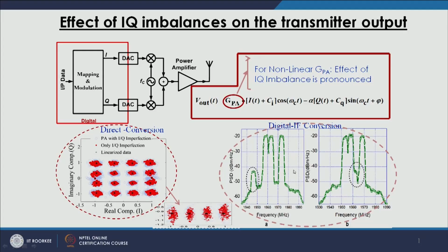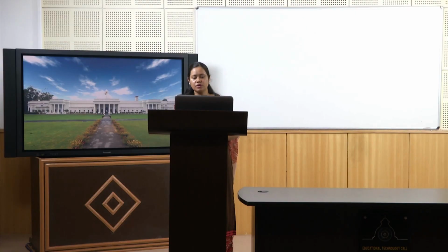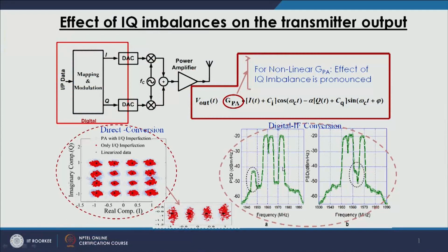If we look at this graph, our center frequency is 1.9 gigahertz here, and the signal is IF shifted by 5 megahertz here. Because of that, the signal was around 1.96, and this is the IF shift. Because of this IF shift, around it an image will appear for this signal. So, how will this image work?